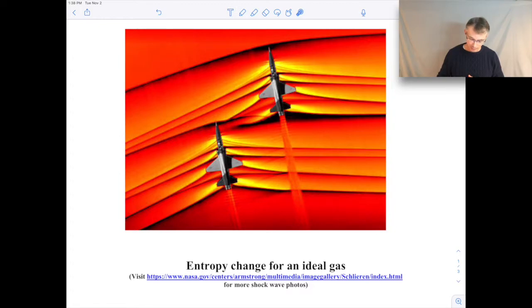You see all these different colors, and in particular these black lines that emanate from surfaces on the aircraft. The colors here correspond to the gradient in the air density flowing around it. It comes from a technique called Schlieren photography. It's not something we'll cover in this course, but if you do any course on compressible gas dynamics, compressible fluid flow, you'll talk about Schlieren photography, at least at some point in that course. But it shows where the air density is changing very rapidly.